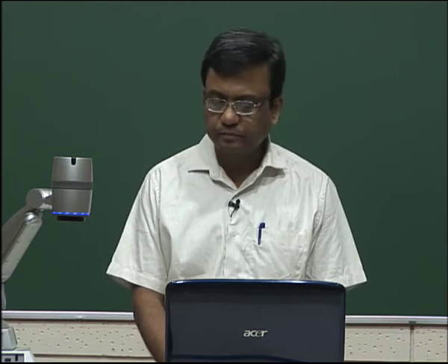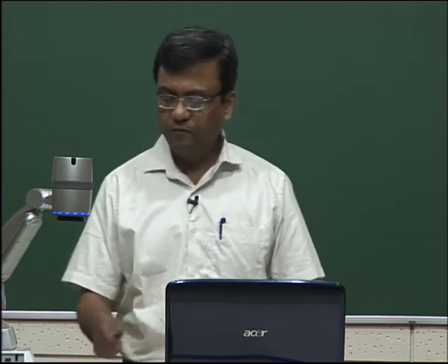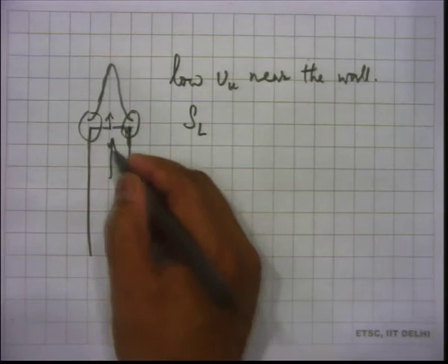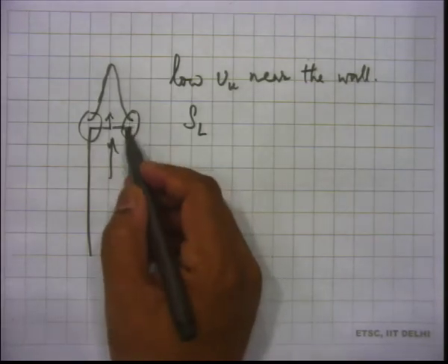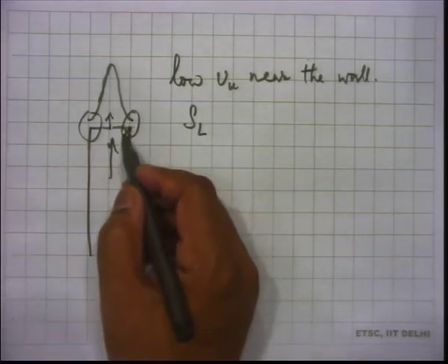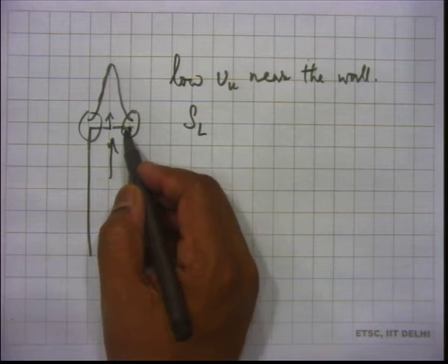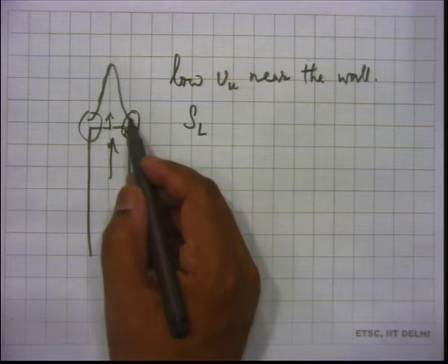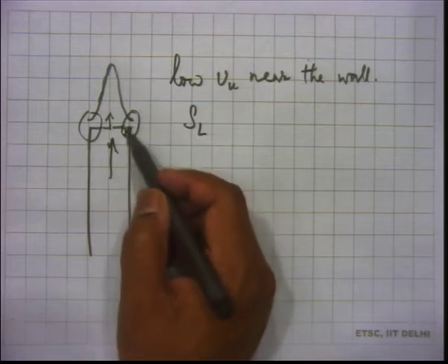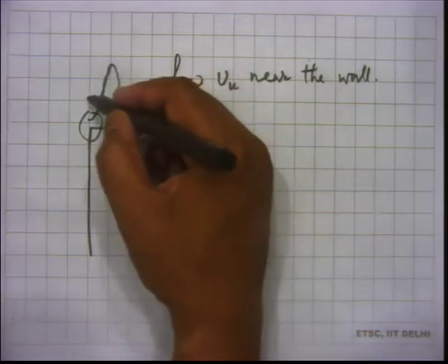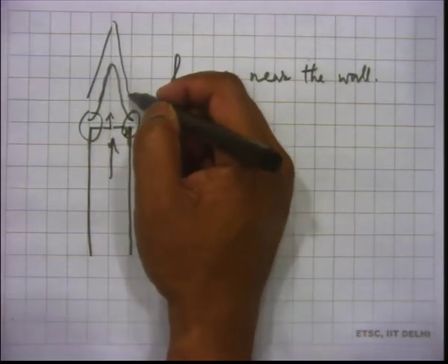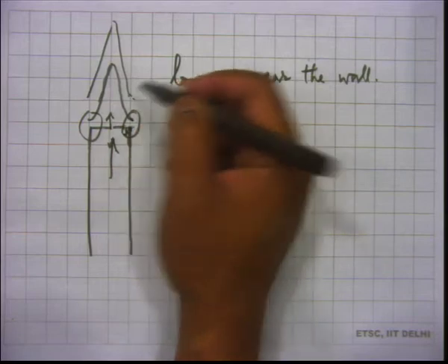If you increase the flow velocity, the flow velocity in this region near the rim actually goes up, and the laminar burning velocity is still low because it's near the wall, losing heat. So the flame tries to move up to some other position where the losses are less. That is an advantage for the flame.